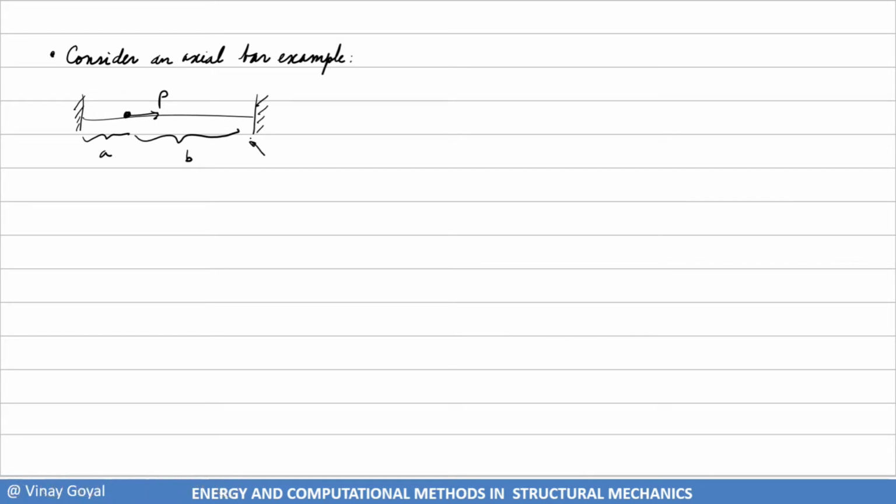So let's remove that support and just say, okay, well, perhaps I have this situation now. And at this boundary where I remove the support, I can replace the support by a load Q, and there must be a deflection associated with that load Q, delta Q, let's call it. But we know that delta Q is zero.